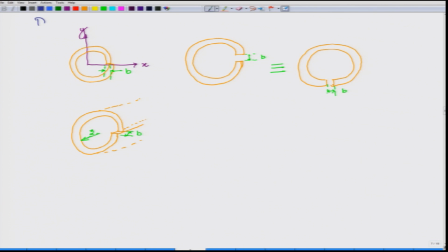So, this is what we have about dislocation using the Volterra model. Now, as you can already realize, the first three that you have drawn here have some similarity. There is no screwness, there is no screw component in them, and therefore, from what we have understood about dislocations, this is edge dislocation.